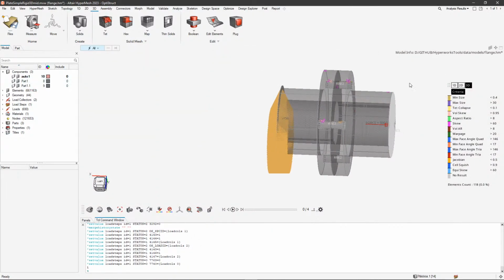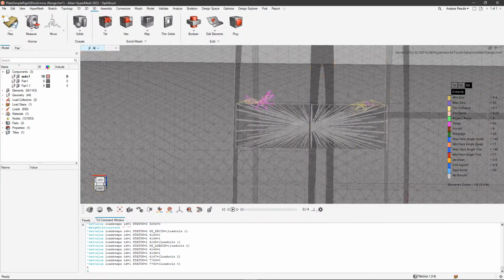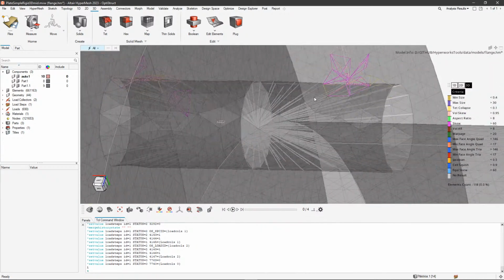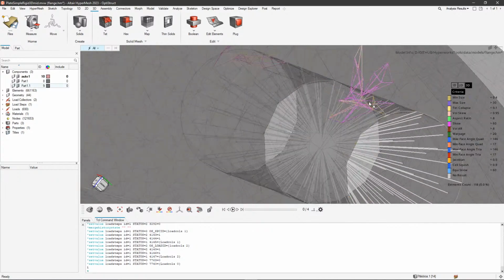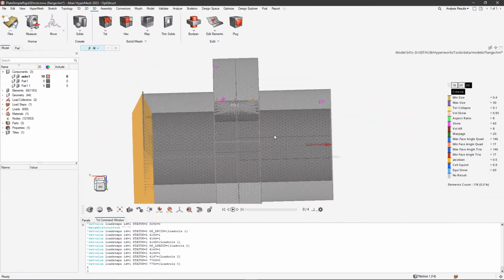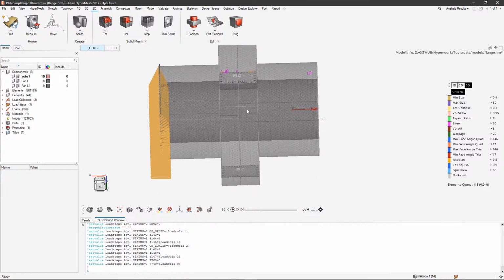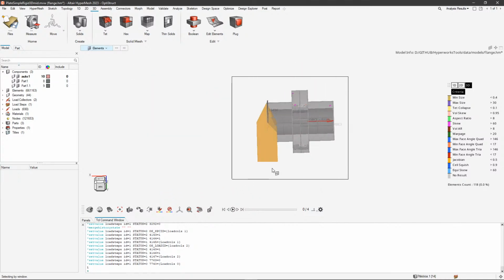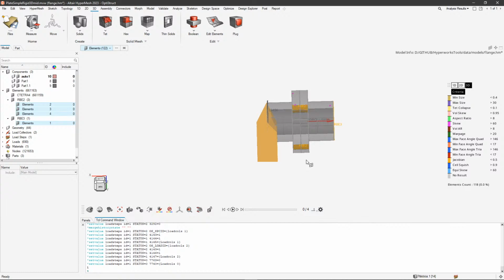And the problem is if you have something like this, you have to do the things again. Normally, because I thought the geometry shouldn't look that bad. I would not have thought that it would have such a bad problem here, but yeah. I think I will have to do a little bit more. I'll just delete the elements. But you see, you have to do the rigids again. You have to do the RBE3 again, the forces again, all that good stuff.